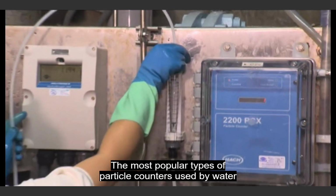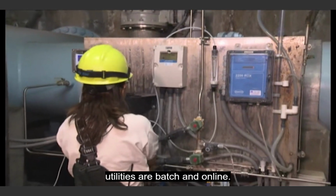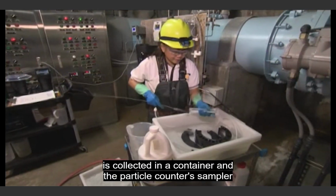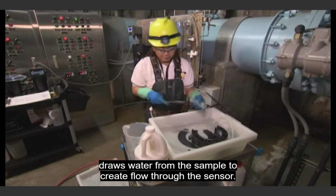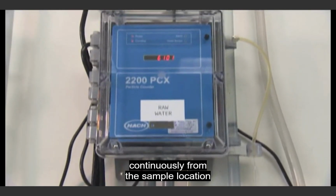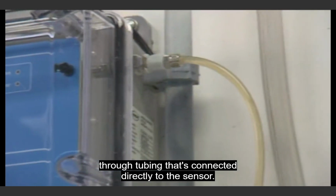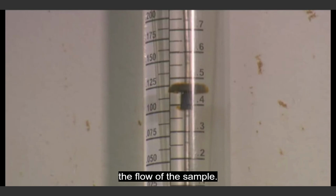The most popular types of particle counters used by water utilities are batch and online. With batch particle counters, sample water is collected in a container and the particle counter's sampler draws water from the sample to create flow through the sensor. Online particle counters draw water continuously from the sample location through tubing that's connected directly to the sensor. A flow controller is required to regulate the flow of the sample.